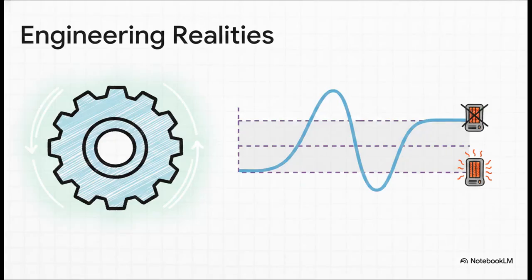To sum up the core engineering realities here, a binary on-off actuator can literally never just rest perfectly at a single set point. It's physically impossible in the real world. So asymmetric switching is absolutely vital. The actuator only kicks on to heat things up when the temperature falls completely below that lower limit, and it only shuts off when it fully breaches the upper limit. This clever design guarantees that the system safely and continuously oscillates within a tolerance we can accept, which totally protects the mechanical hardware from burning itself out through rapid chatter.